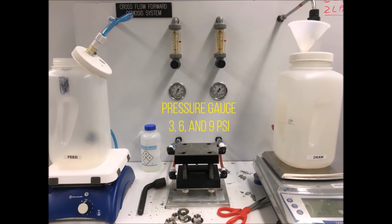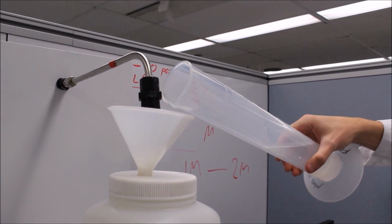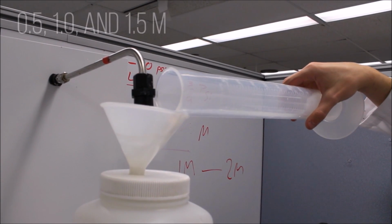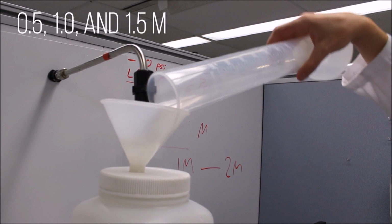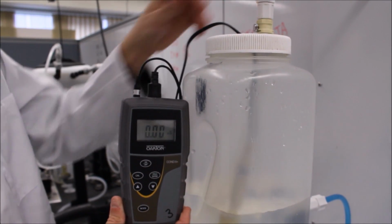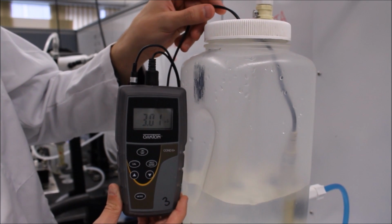We chose to vary the pressure with trials at 3, 6, and 9 psi to observe the change in salt and water fluxes. Measure enough stock solution to obtain the necessary concentration in the draw tank. We also decided to vary the concentration of salt in the draw from 0.5 to 1.5 molar. Once the software signifies that the data has reached equilibrium, add the solution and test the conductivity.